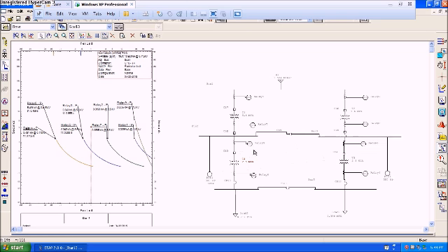As you can see in the graph here, relay 4 and 6 are the first to cross this line. This is the tripping line. These two are crossing the tripping line, and that's the reason they are tripping first, at the lower time. You can clearly see from the graph, this is the curve for relay 4 and 6. They are tripping in less time, so a very small portion is cutting this line, and in the above relays 3 and 5, a large section is cutting the tripping line, because their time setting is greater than the 6th and 4th relay.